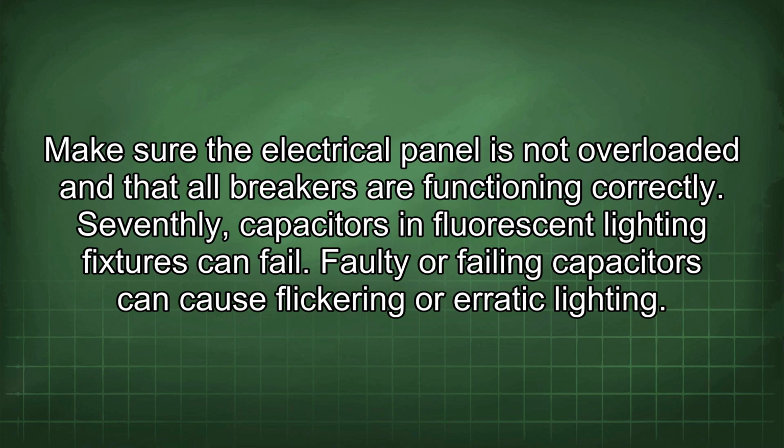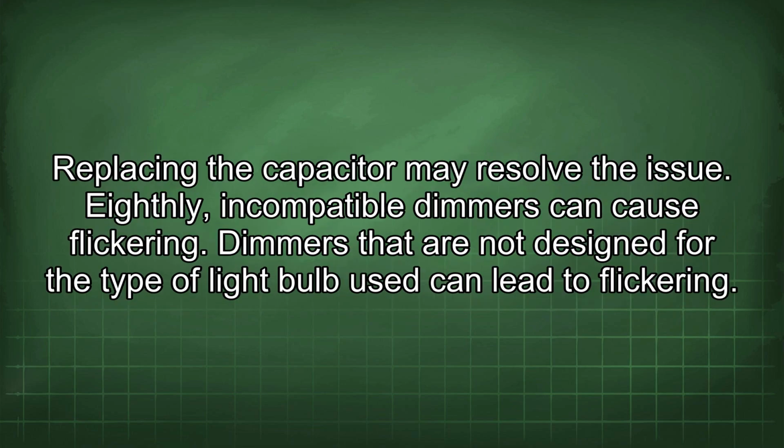Seventhly, capacitors in fluorescent lighting fixtures can fail. Faulty or failing capacitors can cause flickering or erratic lighting. Replacing the capacitor may resolve the issue.